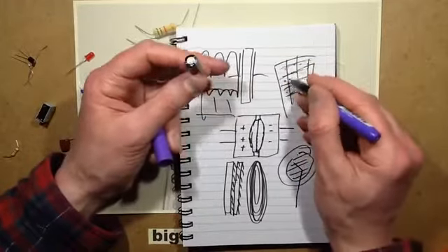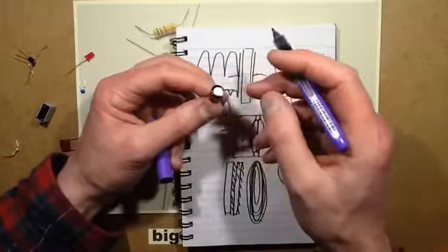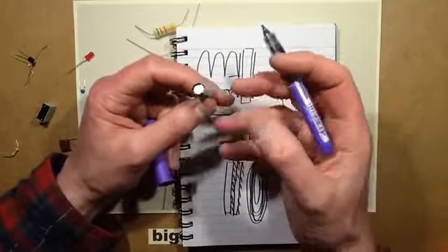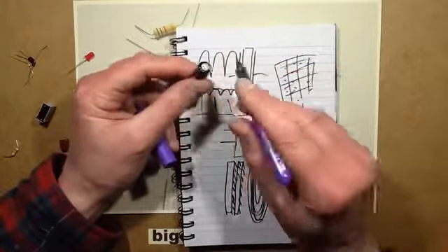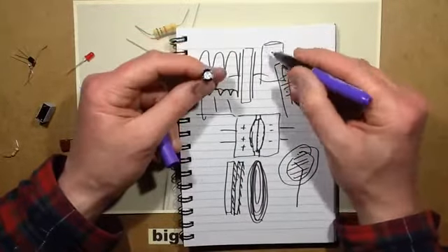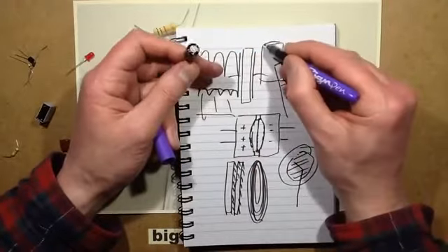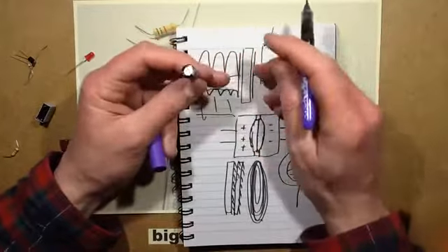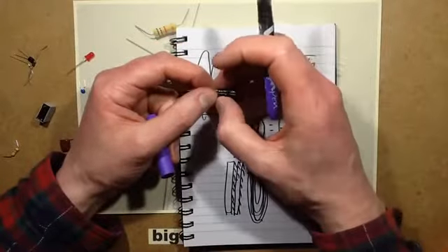When you connect them in reverse, that fails, and then suddenly you've basically got this liquid-filled thing just connected across the power supply with no current limiting it. It turns into sort of a resistor, and it boils the electrolyte. And when that happens, the top will either bulge up, if you looked at it from the side. But if it goes too far, that X that's etched onto the top will split open, and it will vent out the top. And the other option there, if it doesn't do that, is sometimes it blows the whole can off, and it just makes a mess.